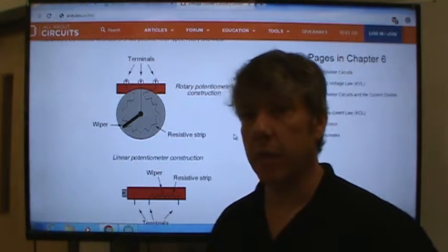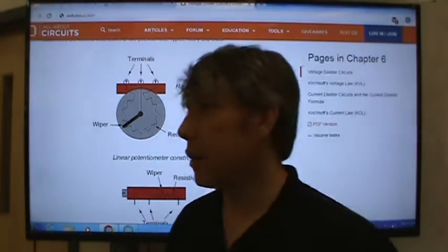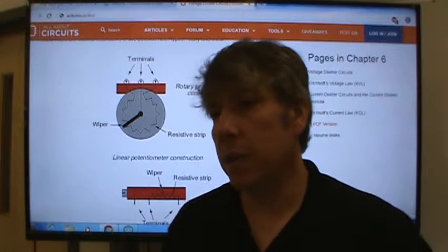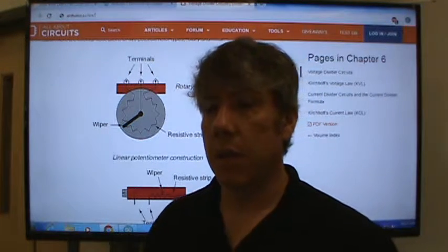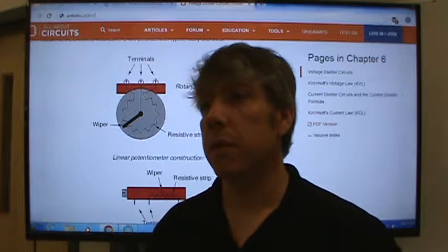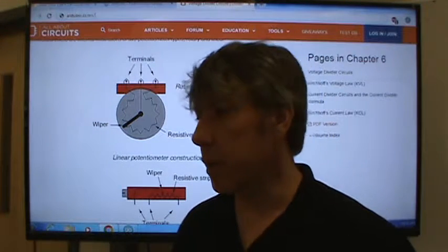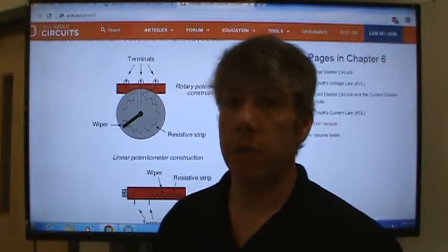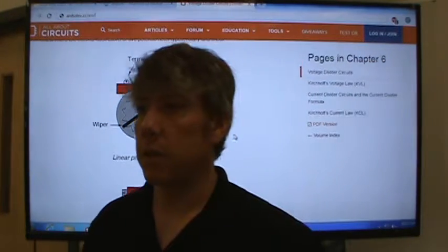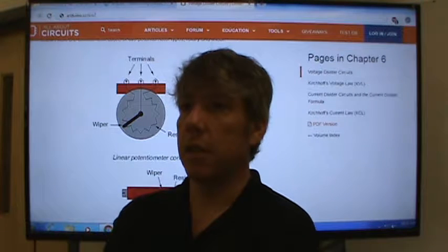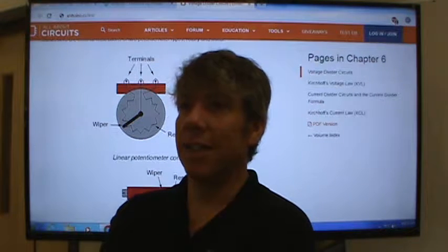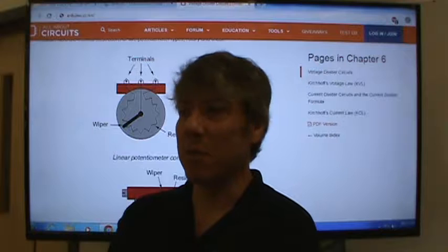And you can see why they didn't waste 16 bits on the input, right? Why would you need 16 bits of resolution? That would be a very fine voltage. In fact, what you'd have to do is take the 5-volt scale and divide it by 65535. You've got a calculator, go ahead and do it. What would the resolution be if they used a whole 16-bit word? About 70 millionths, so in the 100,000ths place of a volt.